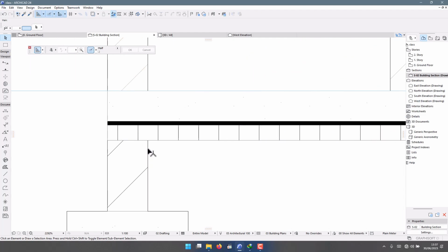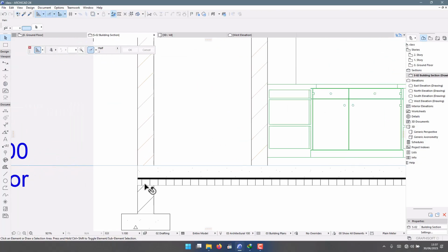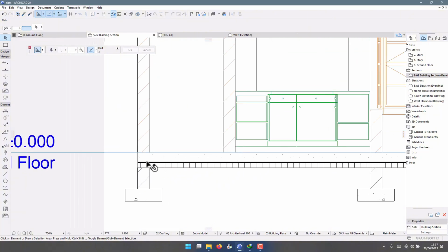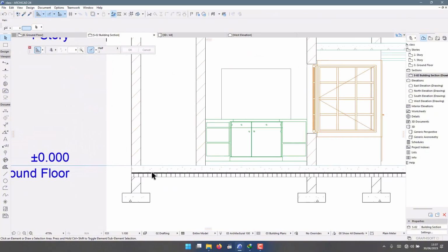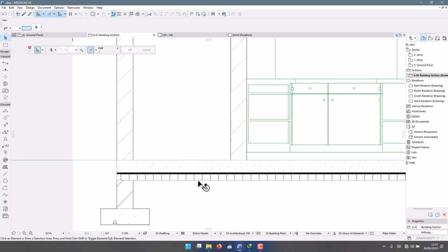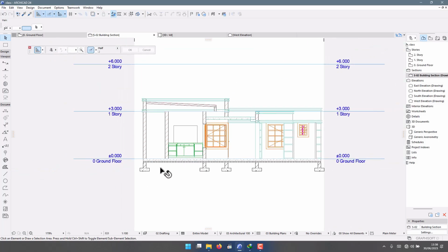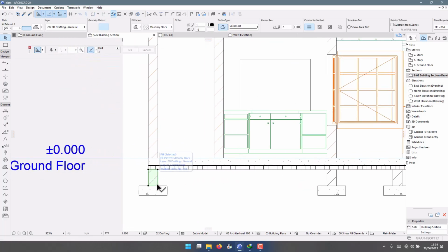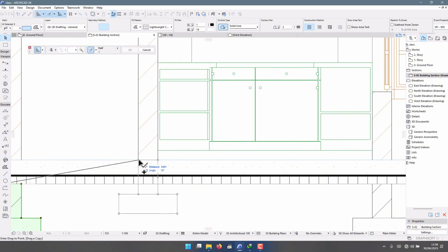I think my wall should have come to this point. Anyways, they know that they're going to pour the slab first before the wall continues. But if you have your wall going all the way to this point, then they know they can build the slab after they have built the building and the walls. So usually make sure you indicate. If you indicate, it makes work easier for everyone, because when they begin construction, they know that we have to go this way.